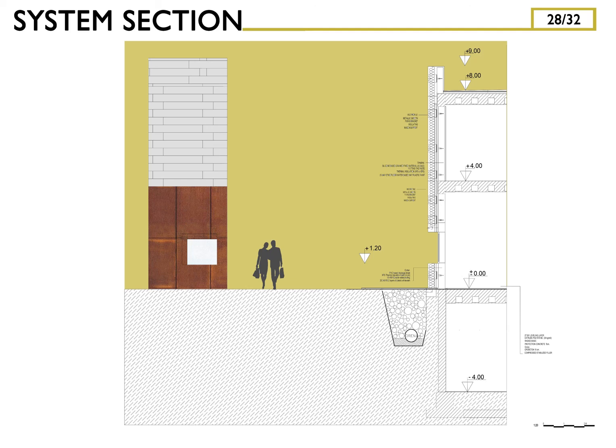The system section shows administration on the west front. Here I tried to show in detail how the material is mounted to the structure. Apart from that, since the west facade is a rainy facade in Izmir, I positioned the drainage pipe on this facade.